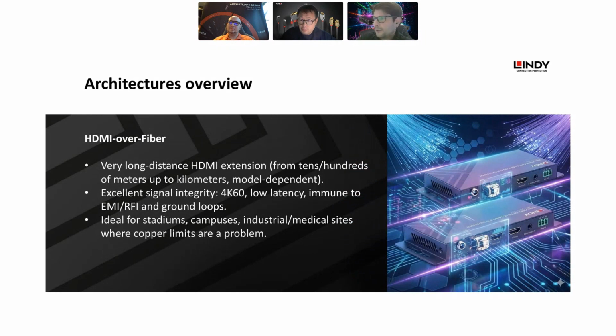HDMI over fiber, if you want to go longer or further. Very long distance HDMI extension, from tens and hundreds of meters up to kilometers. This will be over a single-mode cable to reach a kilometer. Excellent signal integrity, immune to EMI, is the most important feature of this technology. And it's ideal for long-distance campuses, stadiums, industrial, and medical sites where copper limits are a problem.